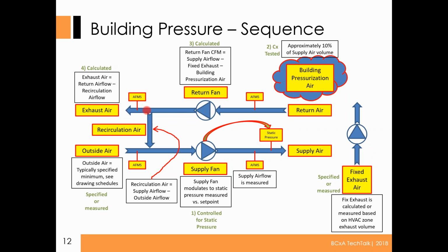And that's where you want to get into troubleshooting mode and say, well, is it doing that all the time, under all modes? Is it only doing that when we're at minimum versus maximum, etc.? So, cause for further investigation. Yeah, and John, he did mention as you were talking that the supply fan was drawing the air in through the relief duct because the return fan wasn't creating enough positive pressure in the relief duct. Right. So I think I guessed close enough.